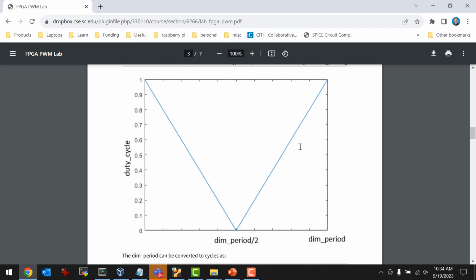But we want to be able to play with that, and change that. The problem, by the way, is if you have a hardware PWM, like on the Arduino, you usually can't change the PWM frequency. It's locked. Unless you have an expensive one, like I think the Intel Galileo had programmable PWM. But a lot of times they'll just say, yeah, it's 25 kilohertz, you've got to live with it. But we have the ability to change that, right?